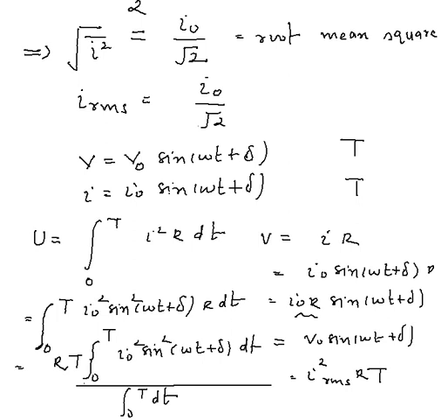If you take the same resistor and pass a DC current of magnitude IRMS for the same time t, will you not get the same energy as heat? To repeat, take the same resistor, connect a DC source so that the current is equal to IRMS in magnitude, DC current now.